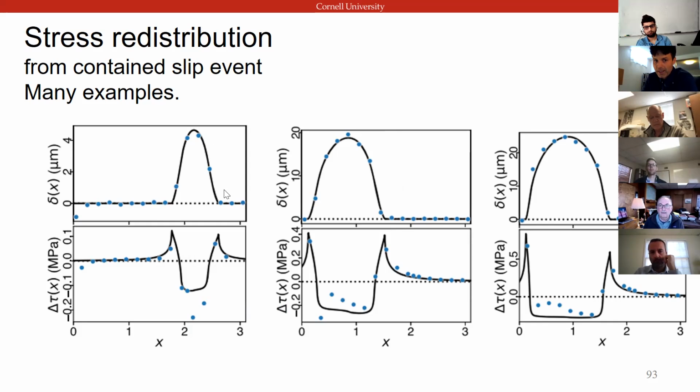So when we get these confined events, we're setting up conditions where it's highly stressed and favorable to rupture at this one spot, and 2 meters down it doesn't want to rupture. The initial shear stress over normal stress ratio is low here. So that's sort of one point.